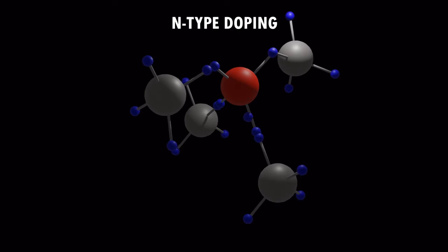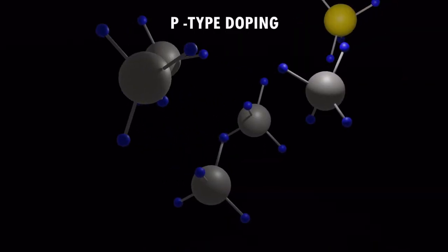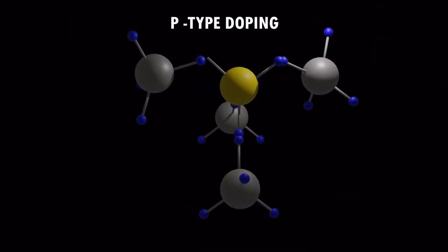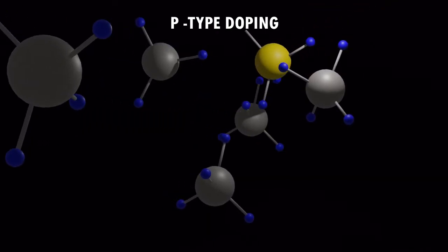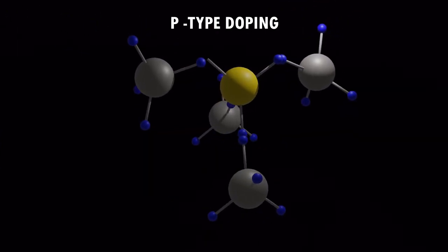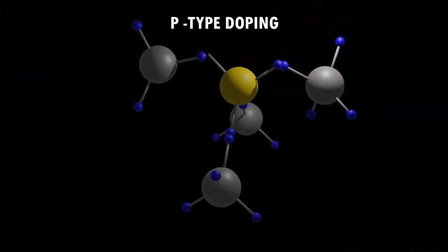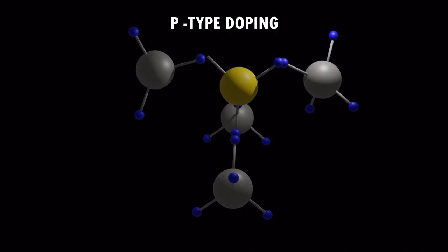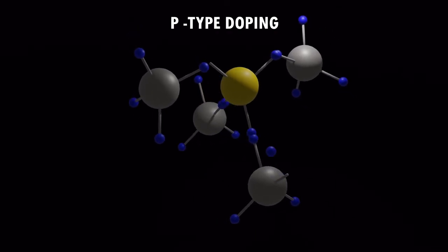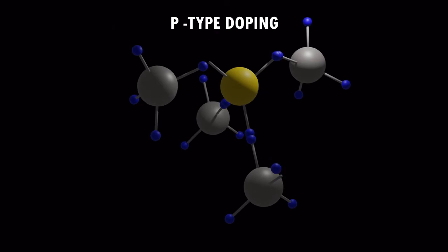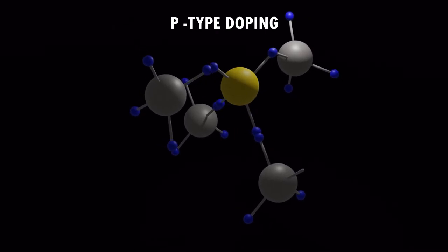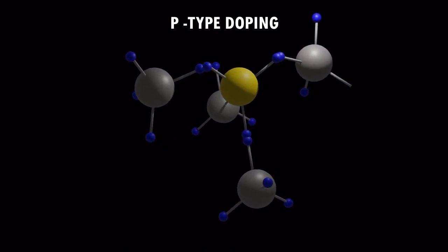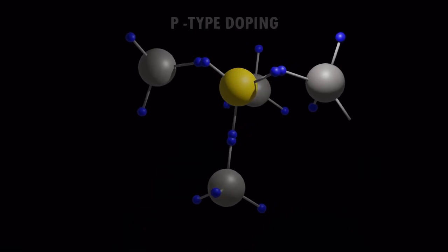There is another type of doping called P-type doping, in which a boron atom with 3 valence electrons replaces a silicon atom. This boron atom requires an extra electron to bind itself to the neighbouring atoms. This vacant position, which is an absence of electron, is called a hole and is given a positive charge. Due to its positive polarity, it attracts electrons from the neighbouring silicon atoms and creates a new hole at another location. This displacement of holes is characterized as the hole movement. As the holes are the mobile charges in this case, this is called P-type doping.